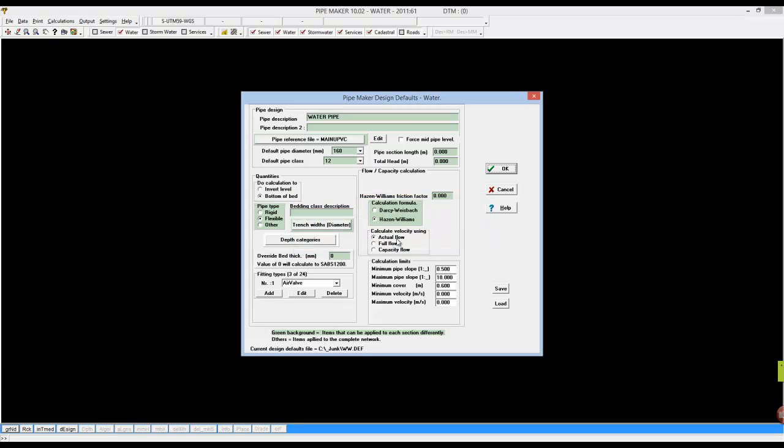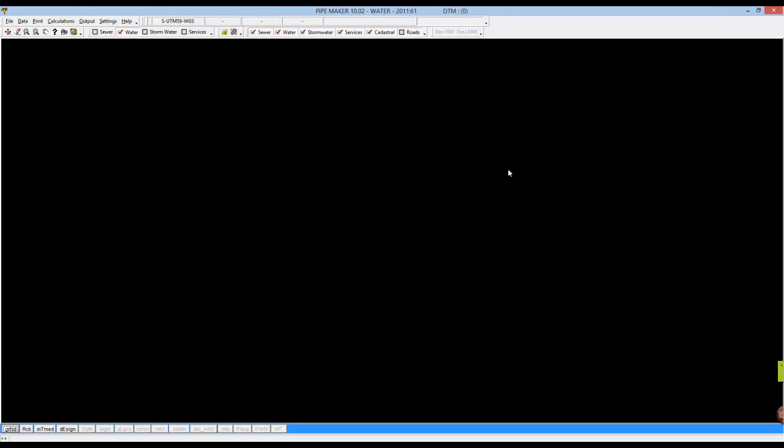It's just moaning about the friction factor. So this is Hazen and Williams. I would probably use something like 140. If you go to the help file here, there are prescribed friction values. 140 would be sort of a medium friction for new and used pipes, so it's quite a nice friction value to use there. Alright, so let's go back to Model Maker.